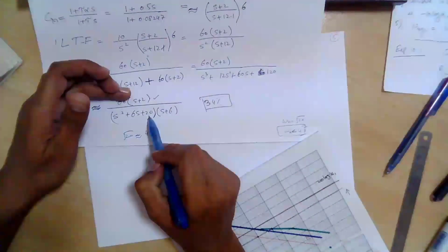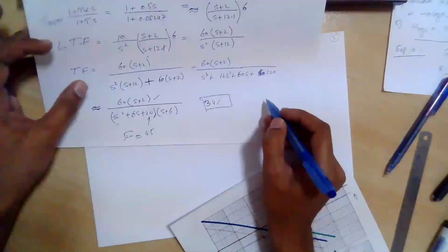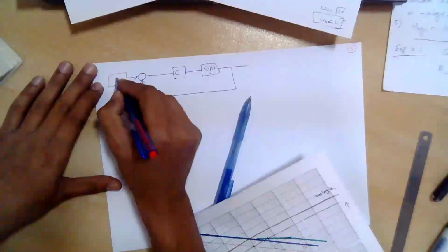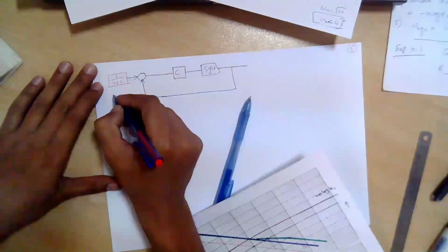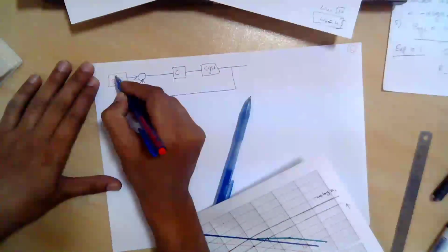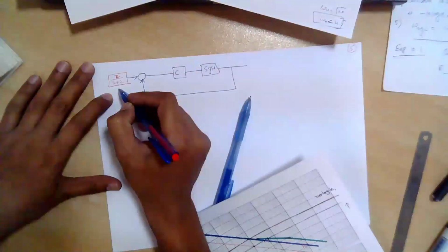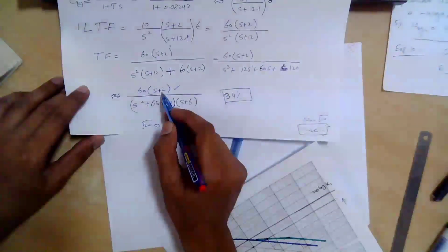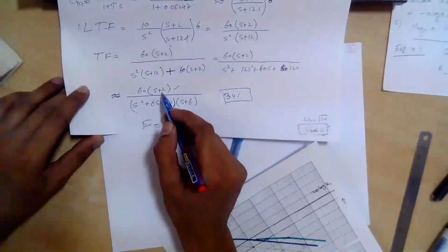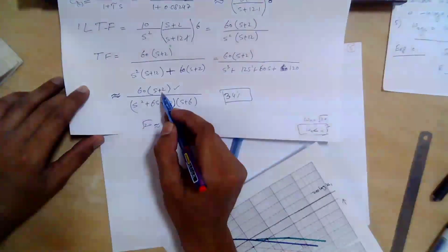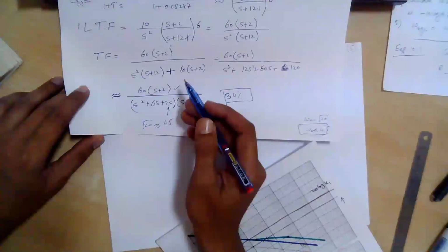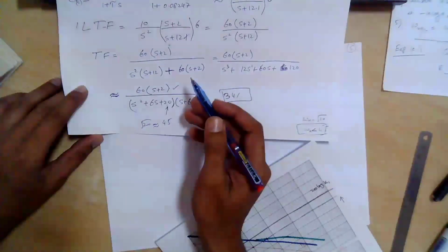So normally what we do is we design the loop and we add a 0 over here and 1 over s plus 2 in the normalized form, 2 over s plus 2. So it's a normalized form. So what it will do, it will kill this 0. And killing a stable 0 with a stable pole, it's not a problem. Unstable ones cannot be done like that.